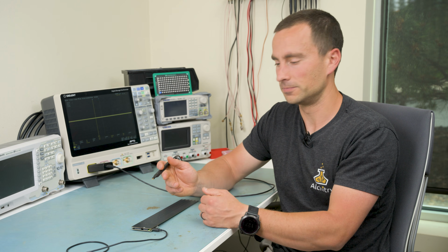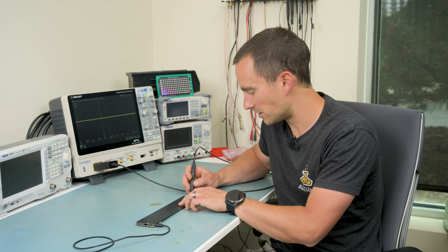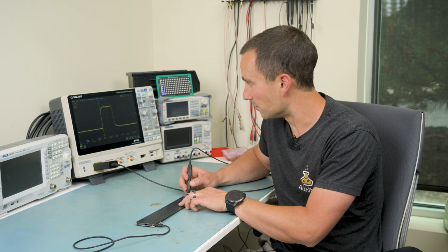Even if you have a really bad mismatch, if it's really short and your signals aren't traveling that fast, the opposite reflection will cancel the first reflection so that it isn't that bad of an issue on your signal. However, if you have a really long mismatch, then it has time for those reflections to get separated, and then they no longer cancel very well, making it much worse. And we can see that here with the short mismatches being substantially better than the single long mismatch. That's more or less what we would expect.